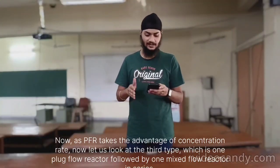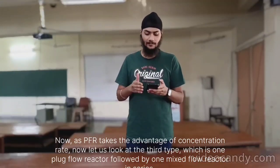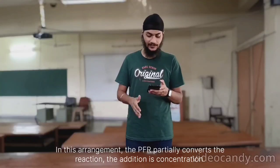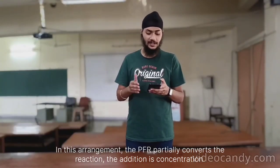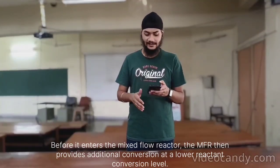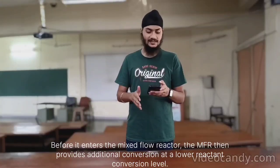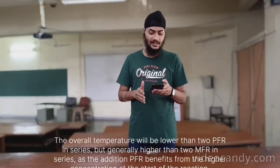Now let us look at the third type, which is one plug flow reactor followed by one mixed flow reactor in series. In this arrangement, the PFR partially converts the reactant, reducing its concentration before it enters the mixed flow reactor. The MFR then provides additional conversion at a lower reactant concentration level.